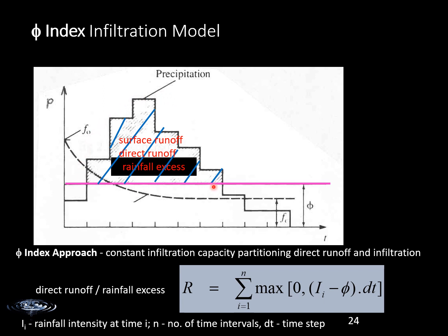Okay, so if it is the outlet of the catchment, we have the catchment here, and at the outlet it may be a small catchment such as a car park, or it may be a big catchment with a stream, right? It can be any catchment. So we measure the direct surface runoff, and we compare the actual precipitation amount with the surface runoff amount. After we deduct all the losses, whatever rainfall occurs eventually has to reach there, right? If not, then that amount is the rainfall infiltration.